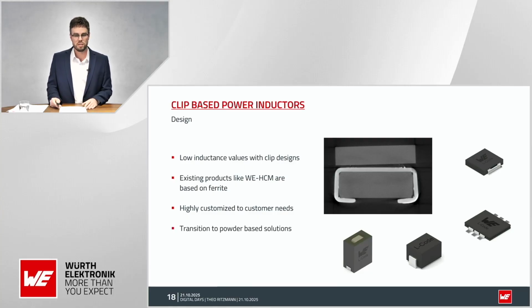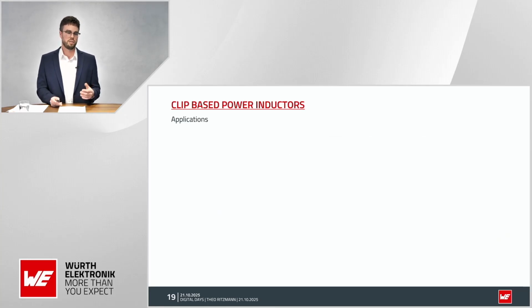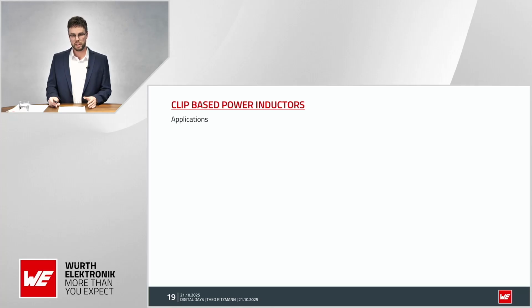Also worth mentioning is that with the increasing requirements regarding switching frequency, temperature stability and soft saturation, a transition currently happens to powder-based solutions instead of ferrite. So in which kind of applications are these products used? The main applications for clip inductors nowadays are the so-called multi-phase topologies. These are converters where single converter phases are in parallel to handle high currents, for example, in server farms, in CPU applications or GPU applications.